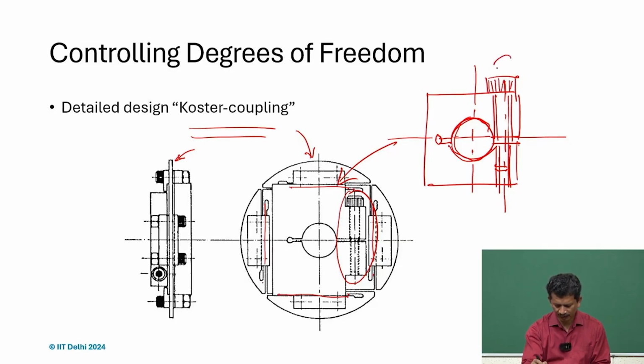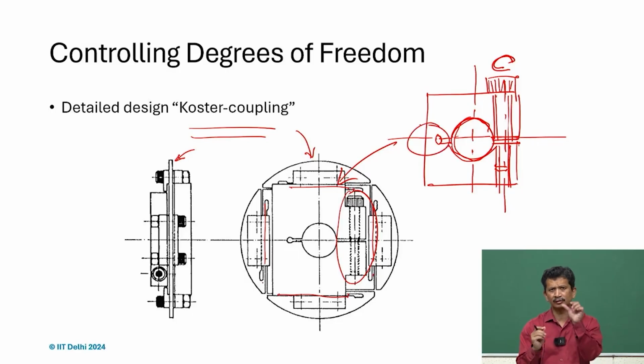What we realize is, the moment we tighten it, this closes, and this part is very important because the thin section will allow that bending to happen. So, these two parts just bend, and as you tighten, it will clamp this surface.